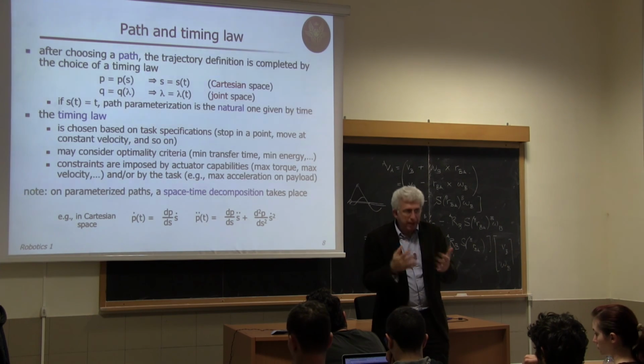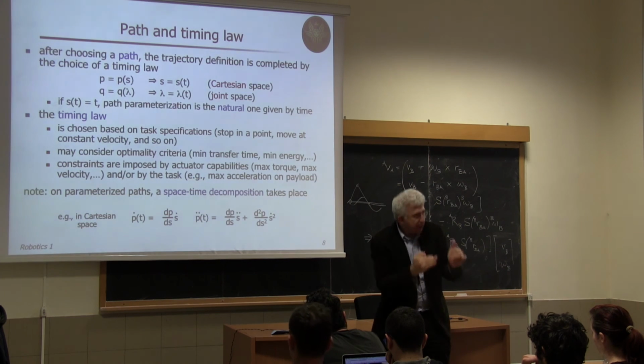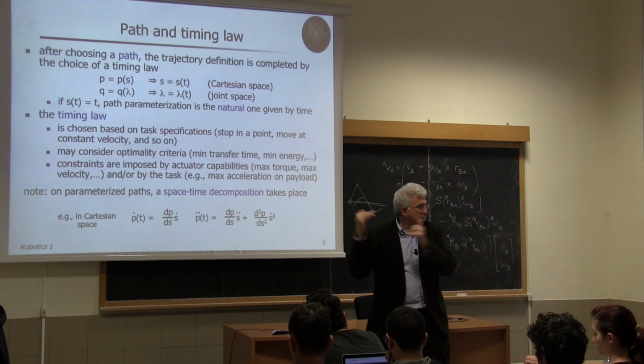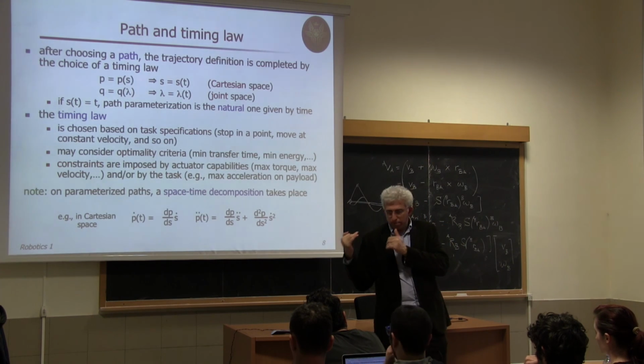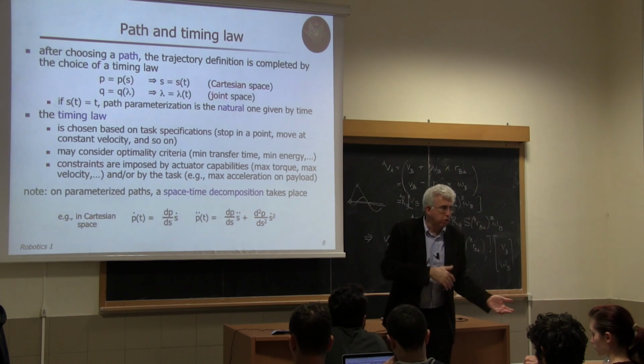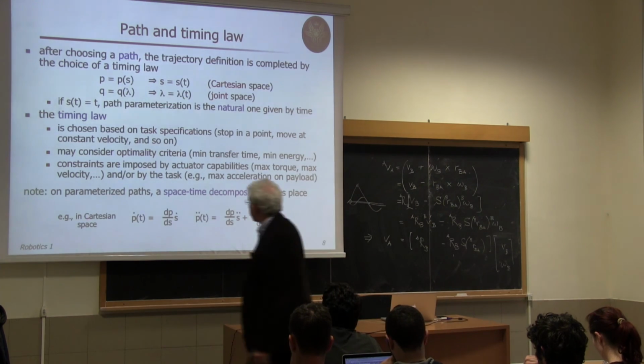And when I'm planning a trajectory, for the same geometry of the path, I need to scale down things, because I have to recover in time my constraint. Okay, acceleration, velocity, Cartesian or joint that they are.